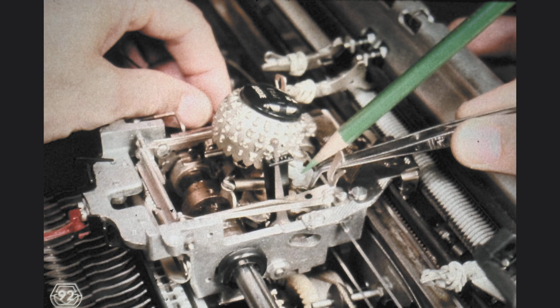Start by installing the tape on the indicated stud on the tilt pulley or tilt pulley sector. Then feed the tilt tape around the left tilt pulley, underneath the escapement bracket, and out through the opening in the right side of the power frame.